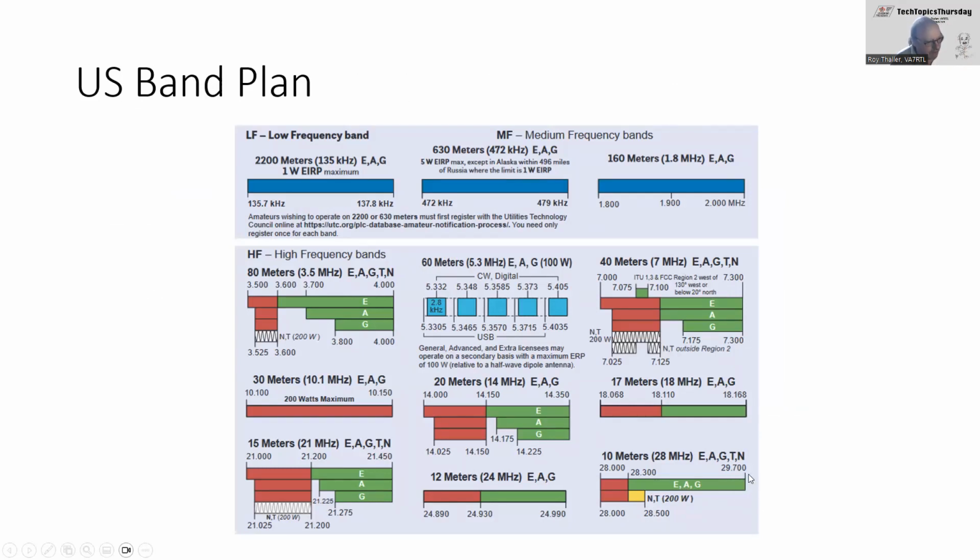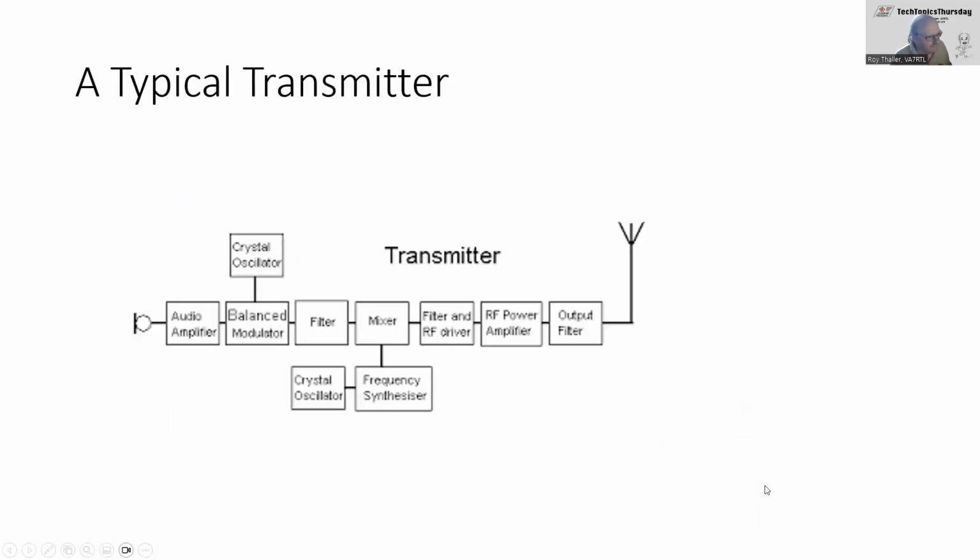And if this is a military band or a police or aircraft band up here, you'll most likely be detected, and then they'll come and see you and say you're transmitting outside of your band. So it's important not to be. If you're doing upper sideband, you need to be below your bandwidth and operating here just to make sure your signal doesn't get outside of that.